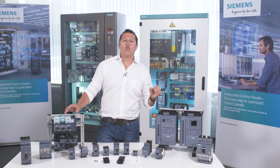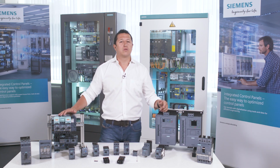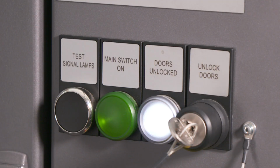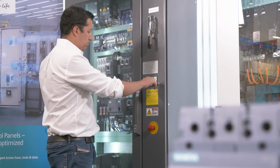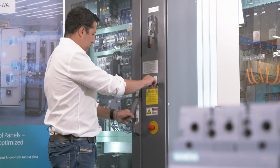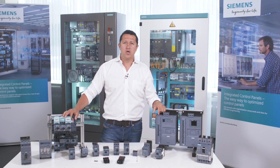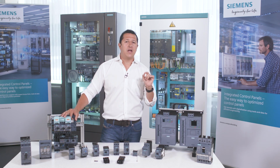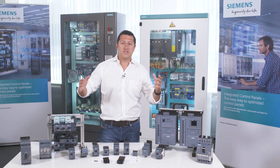In control panels, we often, if not always, need to install components to operate machines without opening the panel. We need to be able to control them from the outside. Openings to the enclosures need to be made, and to maintain the enclosure type or the degree of protection, the products mounted must have an equal or higher rating than the one of the enclosure. Let us see an example.